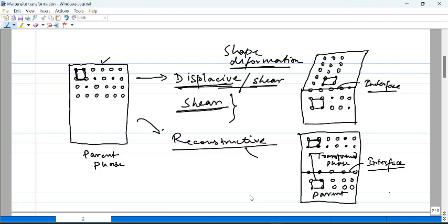Although you see some amount of deformation like this, which is resembling the macroscopic deformation that you would obtain in case of a mechanical deformation or a plastic deformation, but the driving force is different. Okay, in one case, for the mechanical deformation case, the mechanical force itself is the driving force, but here the free energy is the driving force.